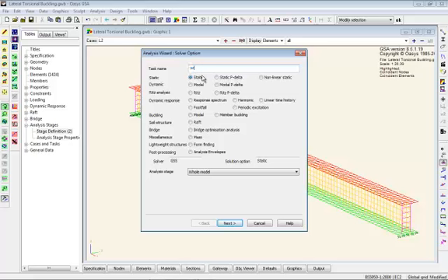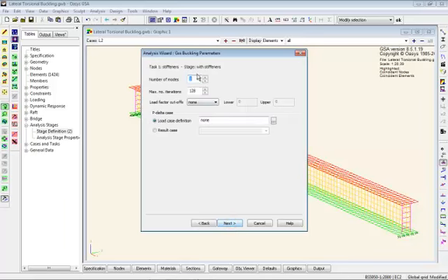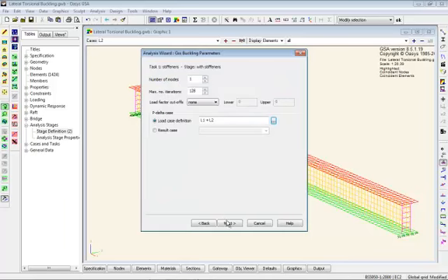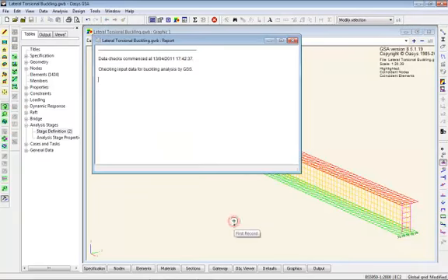I'm going to say a modal buckling on the analysis stage with stiffeners. Whole model and with stiffeners is the same structure, but it's useful to see a bit of guidance. First mode, I'm going to take my loads, and then I'm going to analyse that.